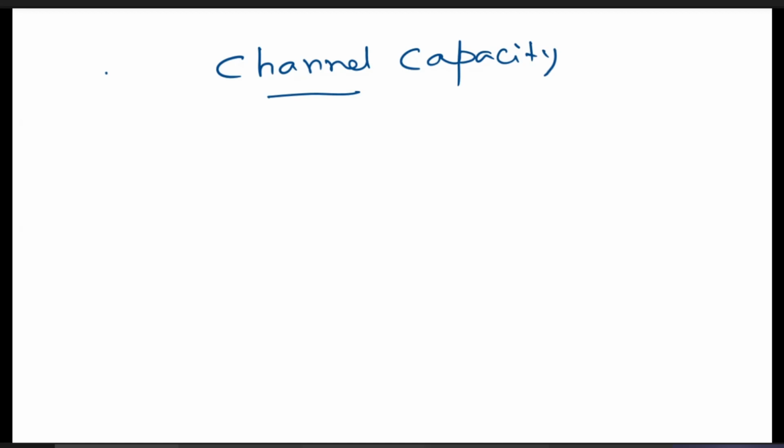And these noises, intermodulation noise, crosstalk, thermal noise, are actually predictable, right? But impulse noise is the noise of very short duration. That may be due to faults or malfunctions in the communication systems, like lightning. At those times, huge amounts of digital data can be lost, right? But it is not so much a problem in the case of analog signaling, as you have seen. So in this connection, one more thing you have to consider is channel capacity, right?